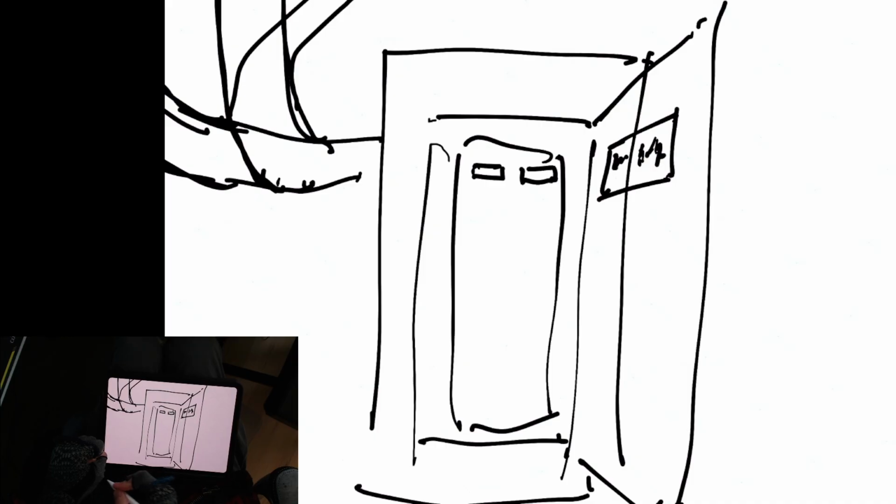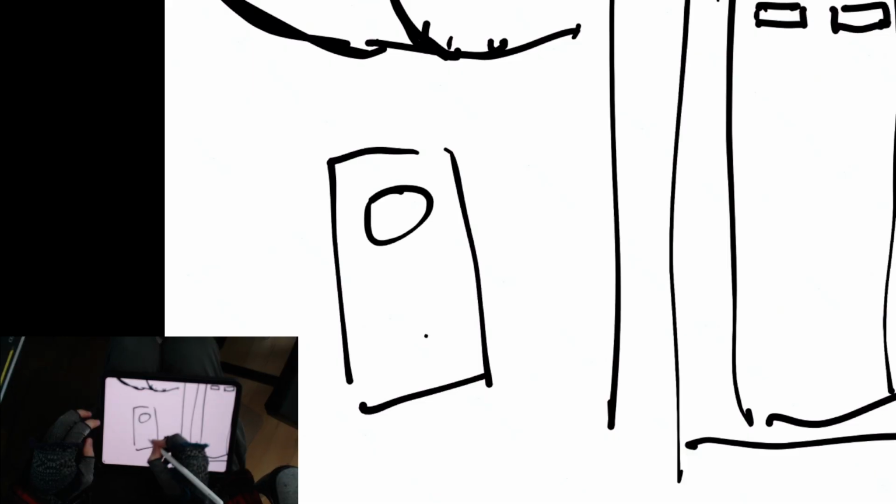If water gets into one of your appliances, it will short it out and trip the breaker at the outlet level. You've seen those outlets with two sockets and two little buttons, one for resetting and another for testing. Those are the GFCI or GFI outlets.